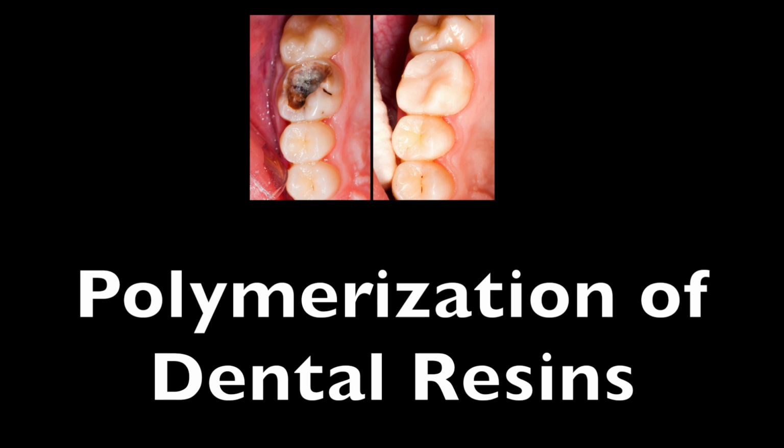So oxygen in the air can actually interfere with the polymerization process at the surface of the resin. How does it do that? So oxygen molecules are really good at reacting with free radicals. They basically scavenge them up and prevent them from participating in the polymerization. So they're like little Pac-Man ghosts, gobbling up those free radicals, running around and eating them all up.